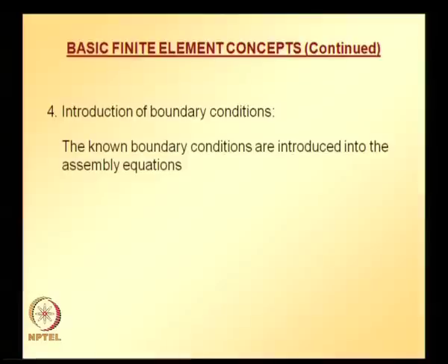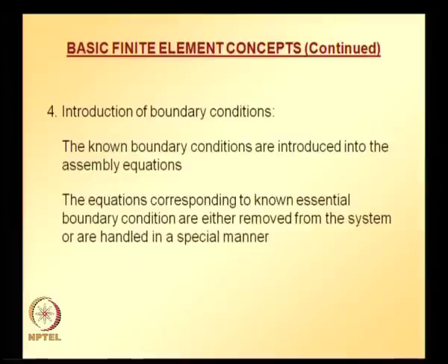As I mentioned, we are going to look at the formal procedure of finite element technique. In this, after assembling the global equation system, we are going to introduce the boundary conditions. The known boundary conditions are introduced into the assembled equations. Equations corresponding to the essential boundary conditions are either removed from the system or handled in a special manner.